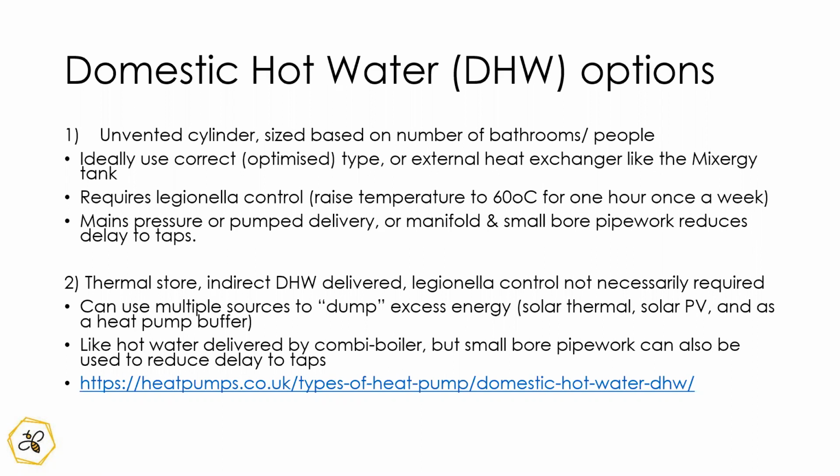You would need some form of Legionella control, and that's generally just an uplift once a week for about an hour. If your heat pump isn't big enough to do that uplift, then that would be covered by an immersion heater.